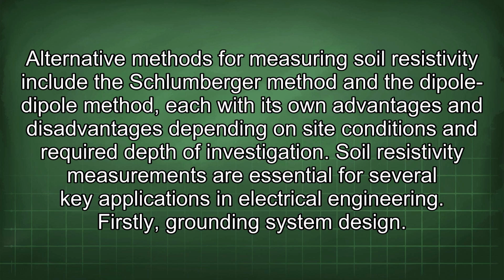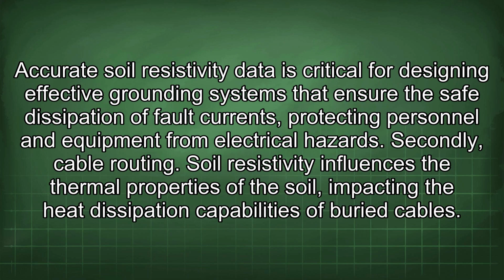Soil resistivity measurements are essential for several key applications in electrical engineering. Firstly, grounding system design. Accurate soil resistivity data is critical for designing effective grounding systems that ensure the safe dissipation of fault currents, protecting personnel and equipment from electrical hazards.